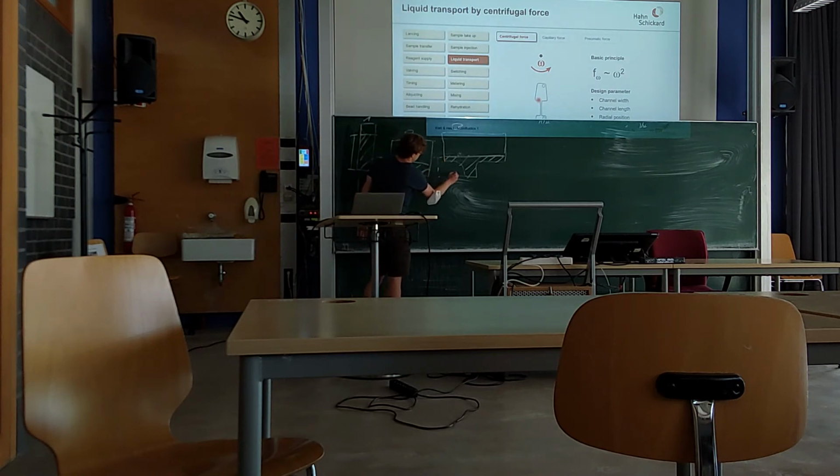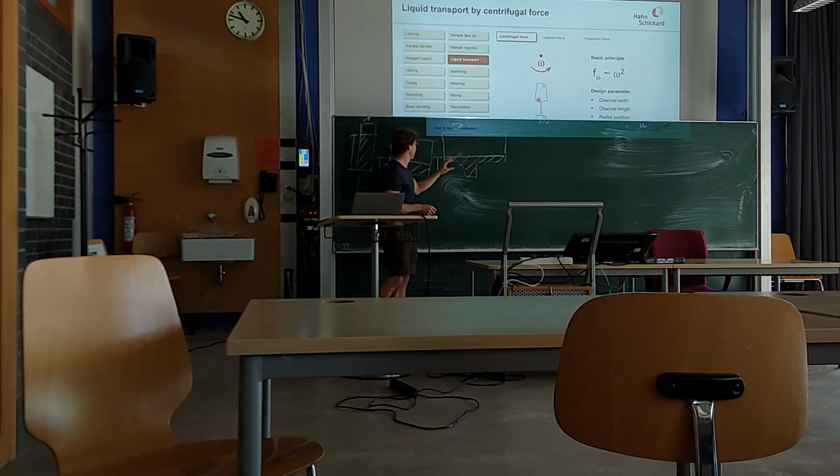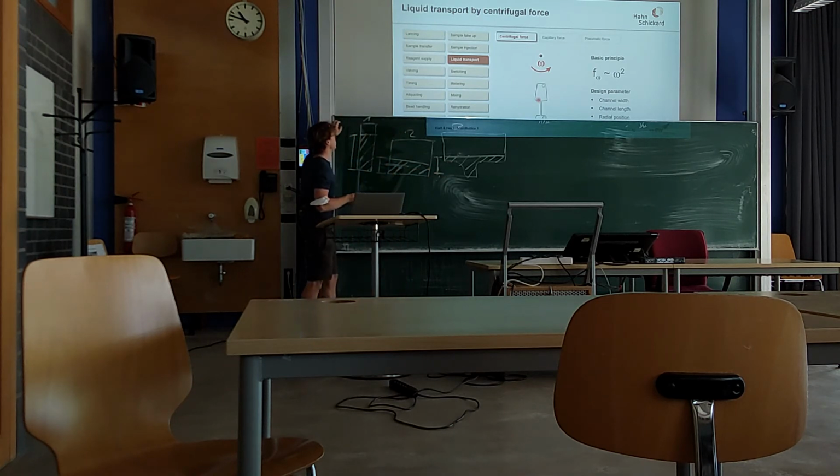So for this chamber here, it's a little hard to evaluate because it's not that easy to fit exactly the same area, but I just wanted to make the point that you can also think about other structures. So by making a smart design, you can influence your pressure and control the flow rates that occur in your microfluidic system.